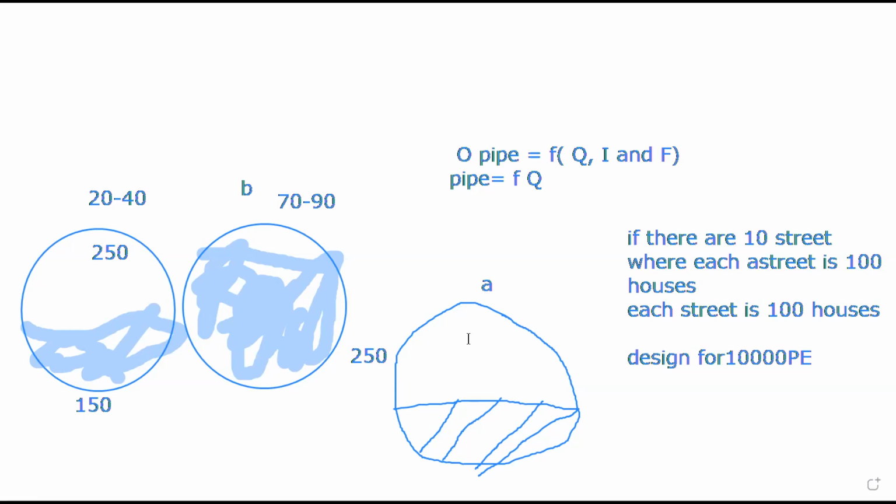The other thing you need to design is maybe the pump and the pump house. But most of the cost goes into the pipe and what it takes to lay the pipe. The labor cost will be based on the pipe length, right? The excavation cost will be based on the pipe length. So you can see that getting this length of the pipe is a very important parameter. And that's why I said at the beginning of this class that everything about water reticulation is about hydraulics, and everything about hydraulics is about pipe sizing. That's it, just to size the pipe.